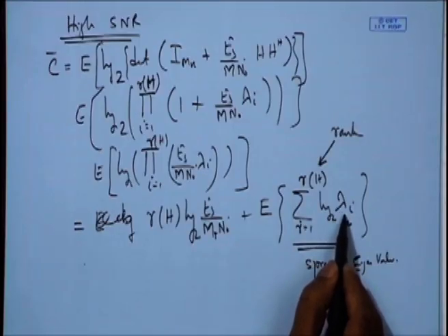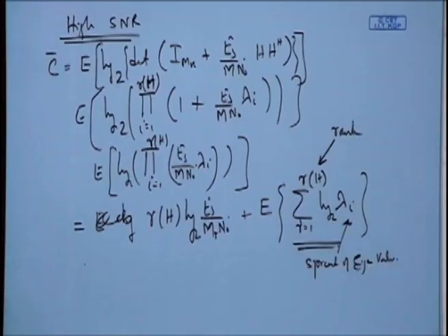So lesser spread of eigenvalues has multiple meanings. One of the meanings is, if lambdas are almost the same, then we are having an orthogonal channel, which we have seen before. And all eigenvalues being the same has another influence. If you have all the same eigenvalues, you can easily guess what would be the result when channel state information is available at the transmitter.